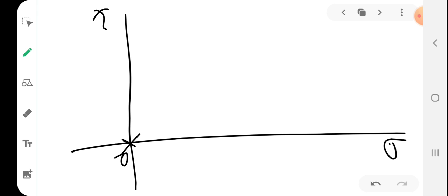Students, now you require a scale, protractor and all. So this is a graphical method. If you draw it in the correct way, you can get the value of the principal stress and the principal plane, the direction of the principal plane and all. So you take this particular 2D coordinate system, where in the x direction we mark normal stress, in the y direction we mark shear stress.